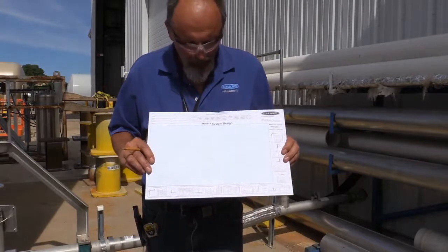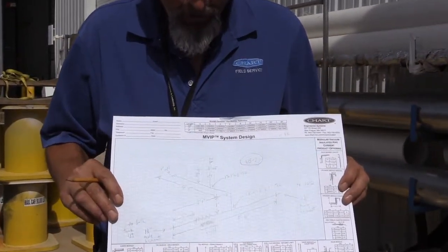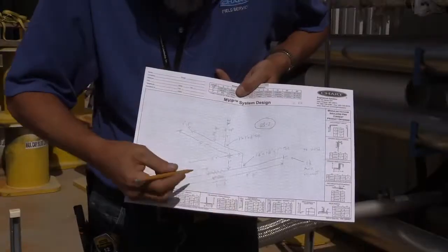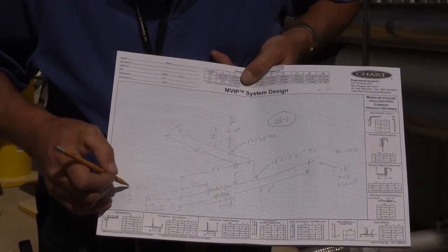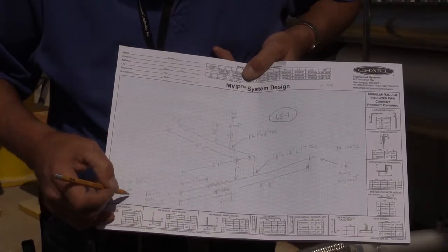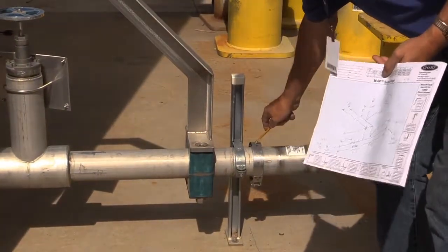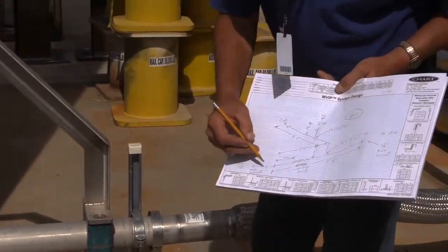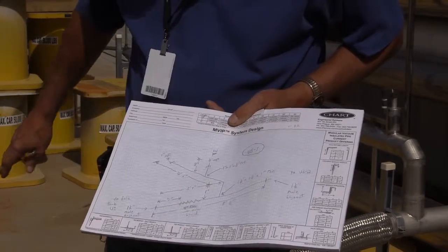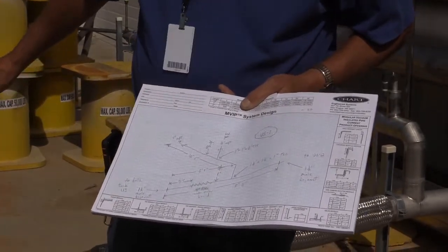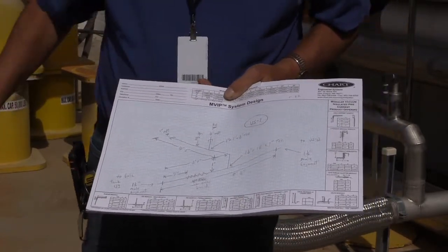The first section we'll measure here is BS1, and I'll explain how these measurements take place. So you see that there's a beginning point on section BS1, and it's clearly labeled, says 2 bulk tank VJ. That would be this piece right here, up to here. This is our bayonet connection. Then I've also labeled 1 1/2 inch male bayonet, because that's what will plug into the existing tank and vacuum jacketed valve and line that is on the tank.